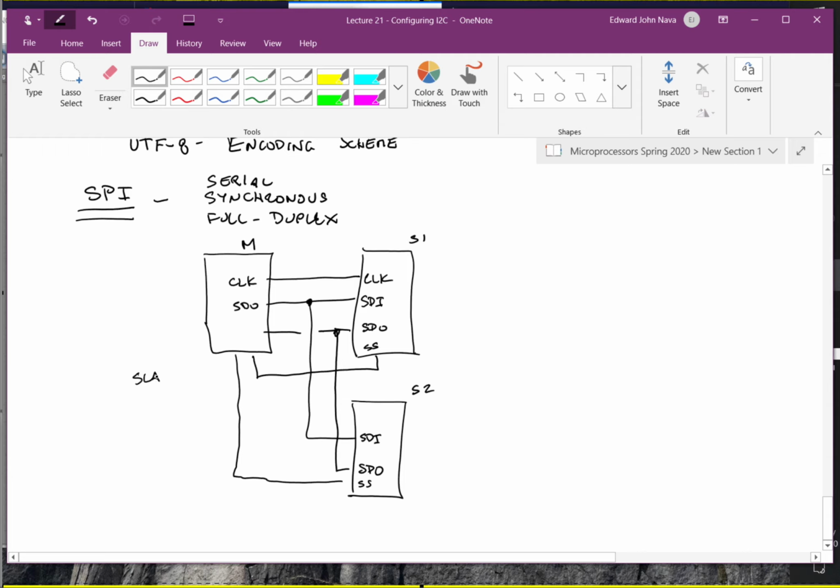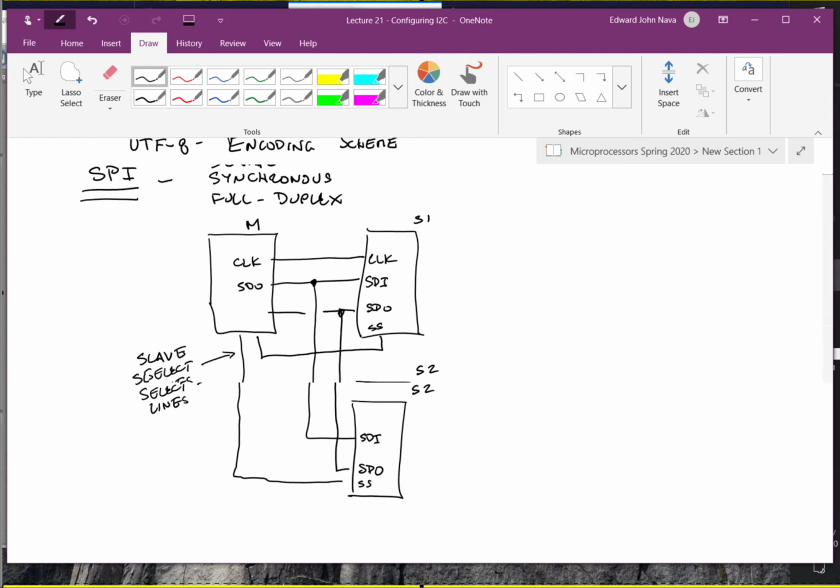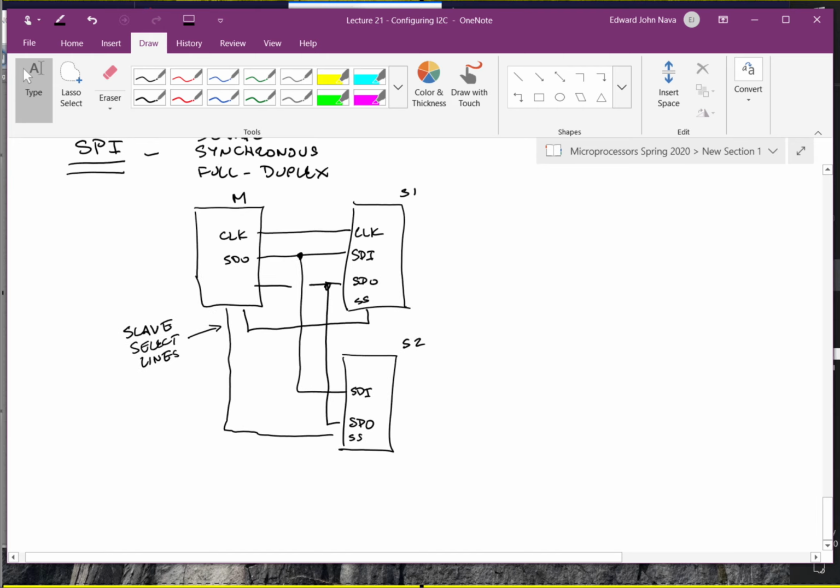So these are, and so because of that, when I use an electrical slave select, now my implementation electrically is going to be a little more complicated, but my communication protocol is very straightforward. We saw when we looked at the signals, they were very, very straightforward, and my implementation now requires more and more I/O port lines to allow me to be able to do this slave select.